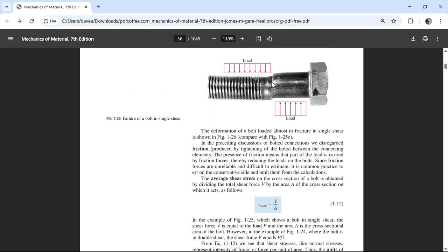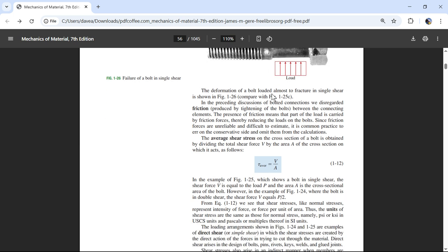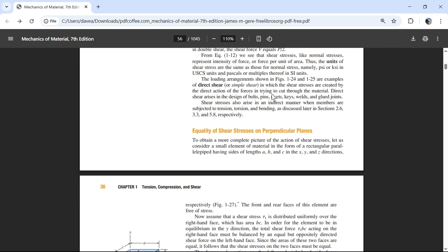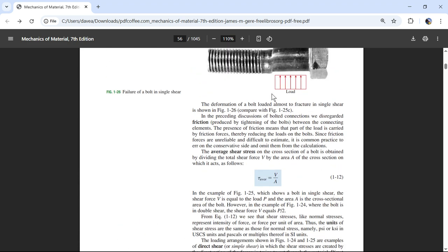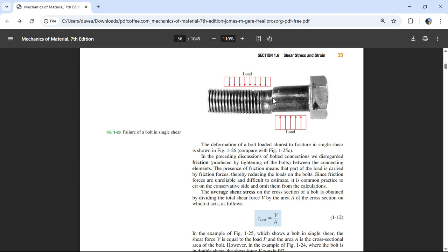We get the same example of pressures, these so-called shear pressures, like lateral pressures developing on that face. What actually happens at this joint, and you can even see it as it deforms, is that a little square chunk is going to turn into a diamond shape.